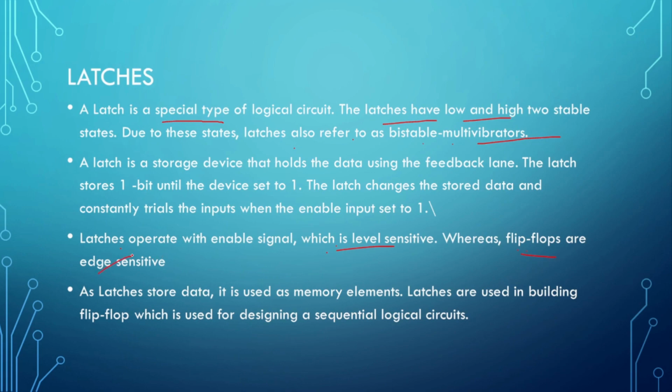Both level triggering and edge triggering we studied in our previous video under the topic clock pulse. If the triggering occurs at a level, it is known as level triggering. If the triggering occurs at the rising or falling edge, then it is known as edge triggering.